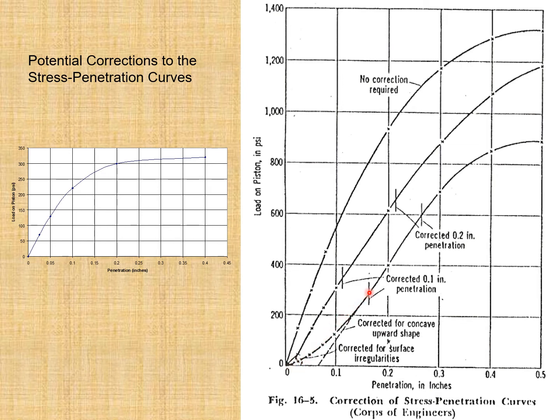So when you are having the upward concave part in the beginning, then corrections are to be applied. Corrections are required. So what we do, we just draw a tangent over here, and in this way 0 will be shifted from this point to this. And if you look at this one, here the tangent will be drawn, touching the horizontal axis somewhere here. So 0 will be shifted from this point to this. So now this will be the 0.